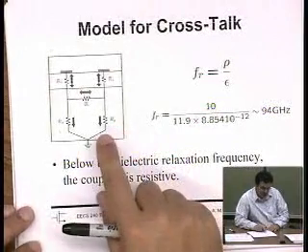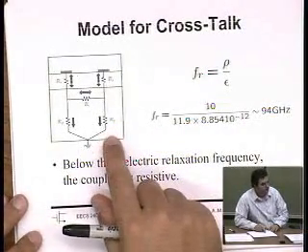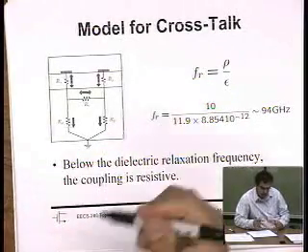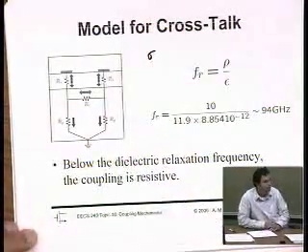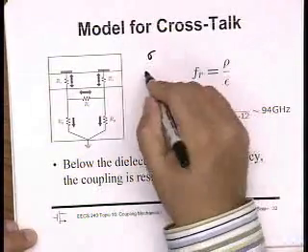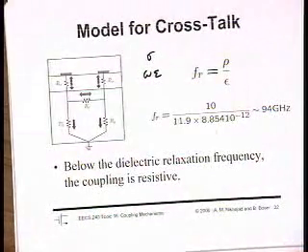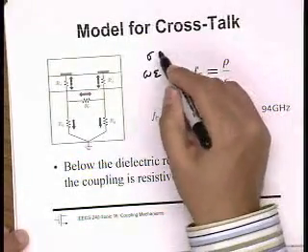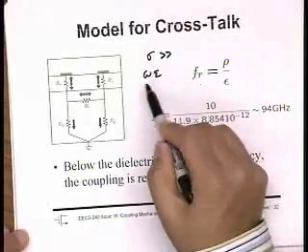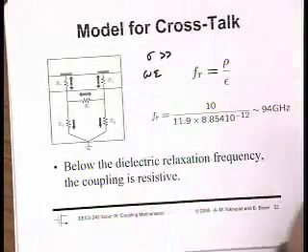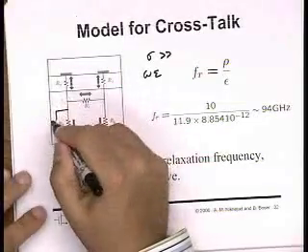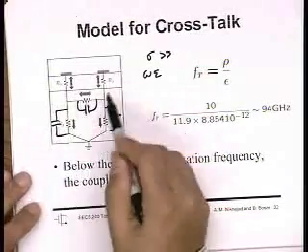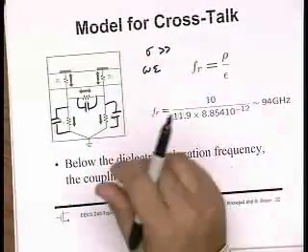Well, it turns out that, in fact, sure, there is displacement current and there's conductive current, and you have to take both into account, right? So conductive current is proportional to sigma. Displacement current is proportional to omega times epsilon, right? And at any given frequency, in a good conductor, this term, the conductive current, totally outweighs the displacement current. Displacement current is nothing but capacitive current, right? That means I'd have to put capacitors in parallel with these resistors and take into account the fact that current is flowing through this material capacitively.